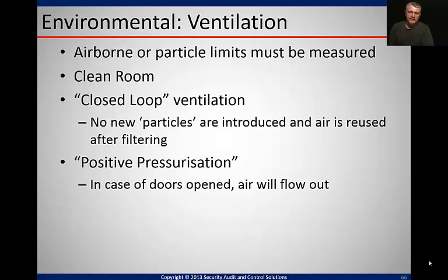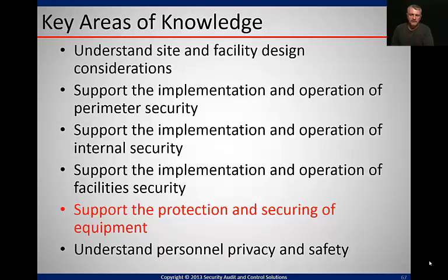Now, when we look at the environment, we have to have ventilation in computer environments, in our data centers. Airborne particle limits must be measured, of course. We could have a clean room depending on what we do. Also, closed loop is a ventilation system where no new particles are introduced and the air is reused after filtering. And positive pressurization means that in case the doors are open, air will flow out.